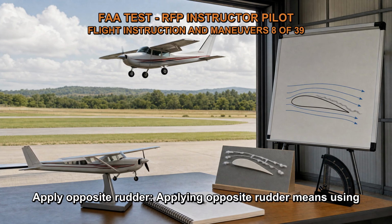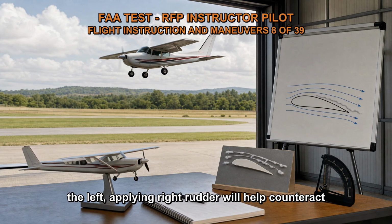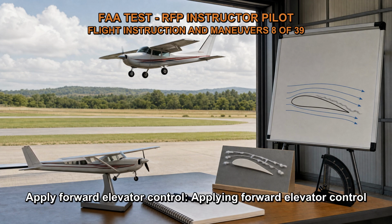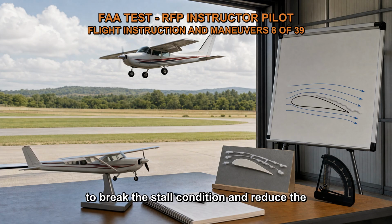Apply opposite rudder. Applying opposite rudder means using the rudder control to counteract the yawing motion of the spin. For example, if the aircraft is spinning to the left, applying right rudder will help counteract the spin and stabilize the aircraft. Apply forward elevator control. Applying forward elevator control involves pushing the control column or yoke forward to break the stall condition and reduce the angle of attack.